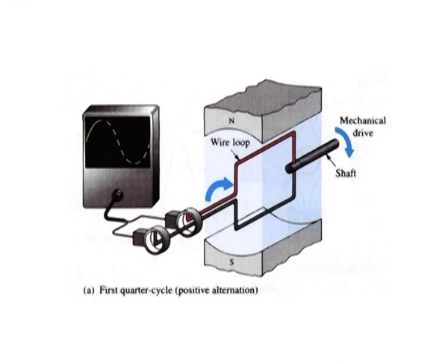To begin, figure A shows the wire loop rotating through the first quarter of a revolution. It goes from an instantaneous horizontal position where the induced voltage is 0 to an instantaneous vertical position where the induced voltage is maximum. At the horizontal position, the loop is instantaneously moving parallel with the flux lines which exist between the north and the south poles of the magnet. Thus, no lines are being cut and the voltage is 0.